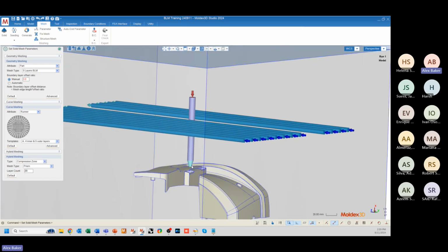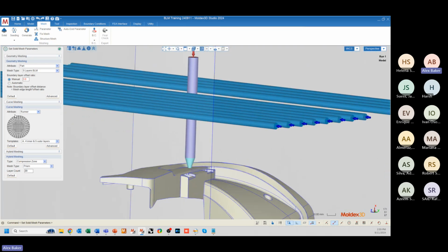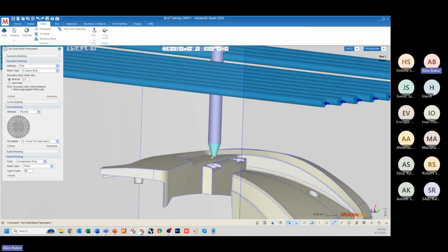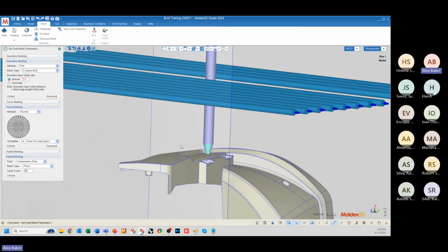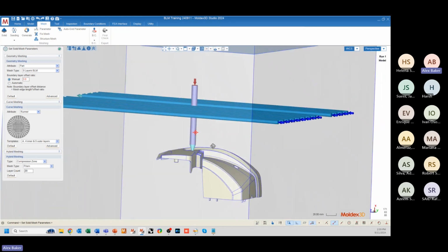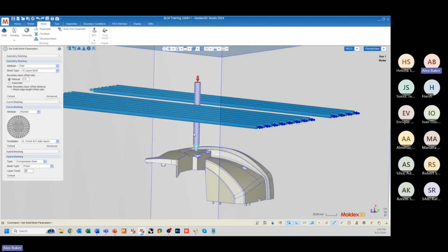So because we're using center lines, we can actually create a two-dimensional profile and then just extrude that two-dimensional profile along that line to create our solid mesh. Kind of like what happens in the boundary layer mesh on the part, but it happens for the entire thickness of our solid, or for our line-defined geometry.